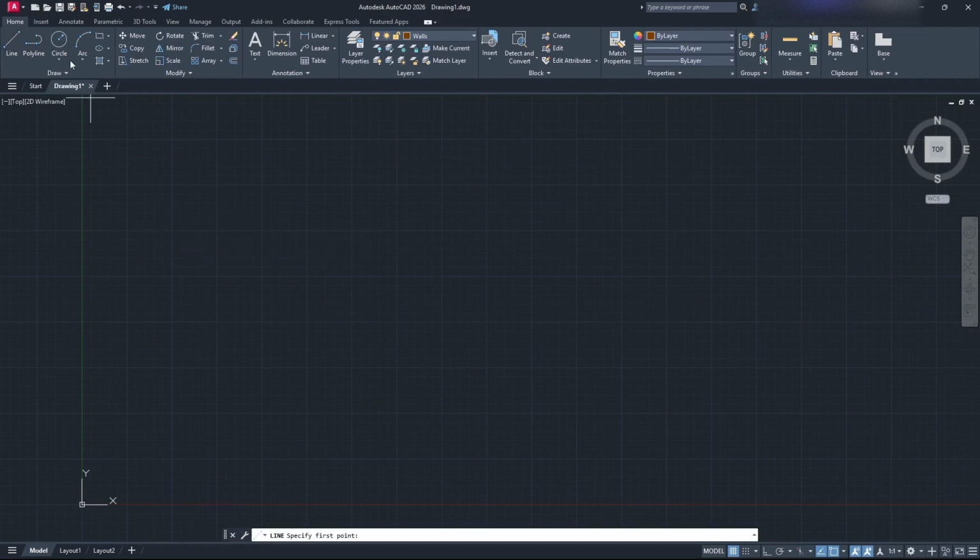So, you got your lines. If you click line, you can also just type commands if you want to use them. So if I type in line, I can see that a variety of tools are going to pop up. If I press enter, it's going to automatically start me on that. So I can come here and click around, and you can see I'm drawing lines.